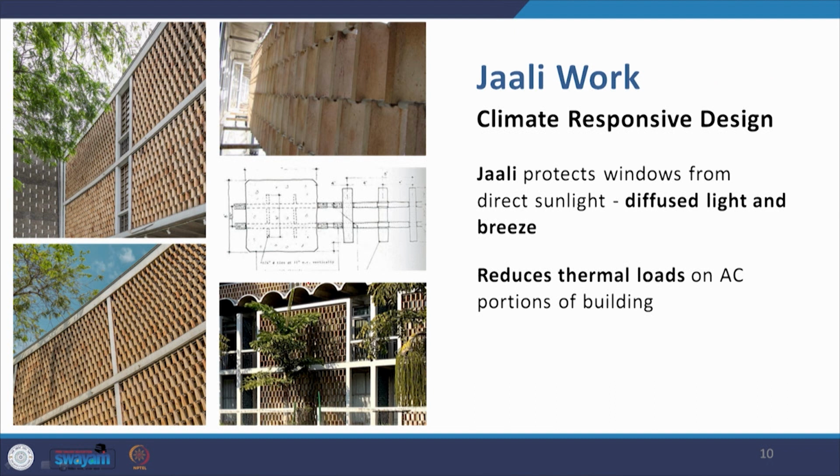Now Jali work is a climate responsive design feature. The Jali protects the windows from the direct sunlight, and therefore diffuse light and breeze enter the building. The entire facade of IIC is dominated by this Jali work, and it also reduces thermal loads on the air conditioned portions of the building.